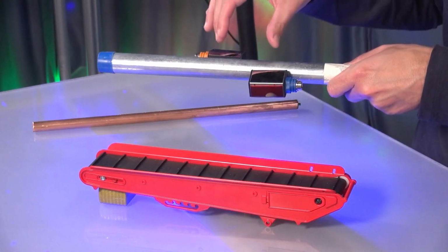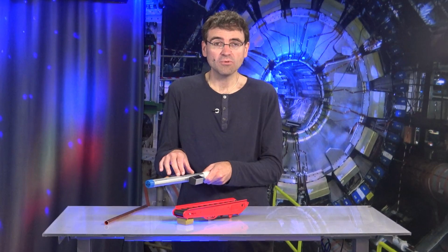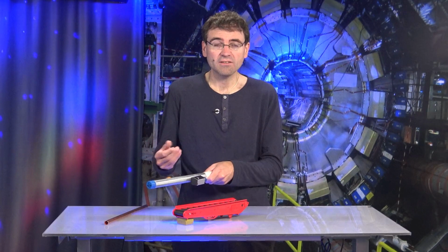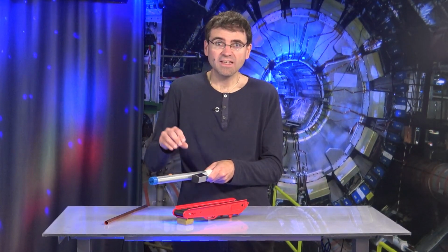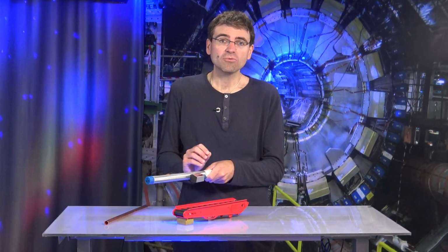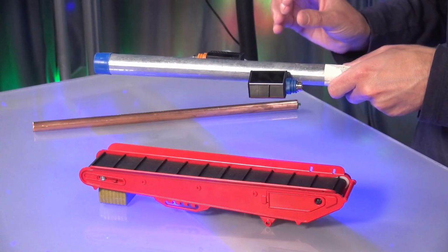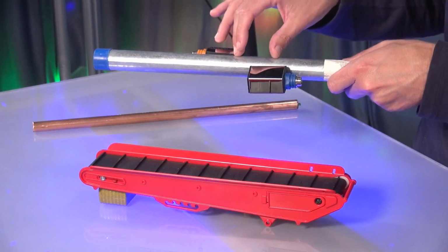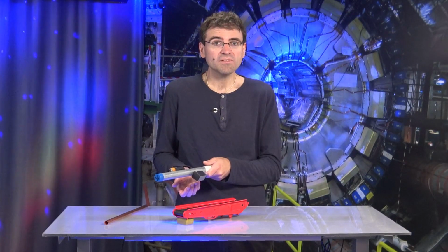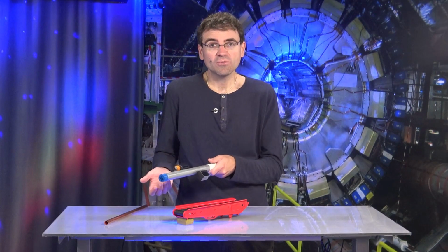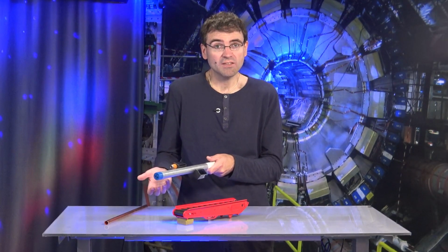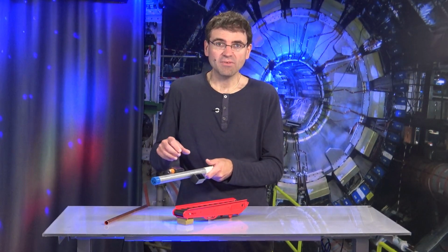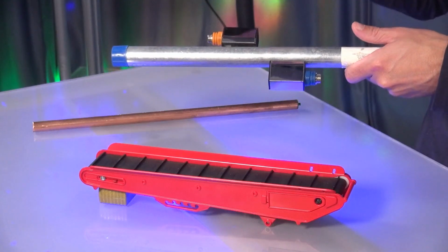It is also important that these probes are mounted horizontally because it is quite likely that the pipe is not completely filled with our medium, which means that there is still some air in our pipe. And as this air is lighter than the liquid, the medium, it would form bubbles at the top. But we do not want to measure the air, as that would clearly falsify our measurement result, right? We only want to measure our medium. And that is why it is important not to attach these probes to the top of the pipe.